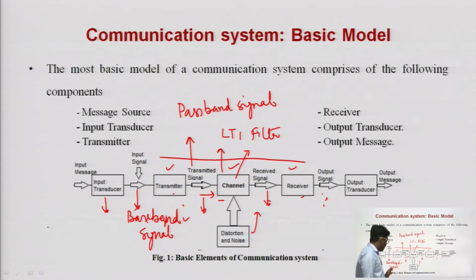When we modify this baseband signal by some process like modulation inside the transmitter, it becomes a passband signal. So, a passband signal is nothing but the baseband signal, but the spectrum of the baseband signal is translated or shifted to a higher frequency range. It means the passband signal contains the same frequency components, but they are translated to a higher frequency range. So, why are we converting the baseband signal to a passband signal? Because the baseband signal has low power.